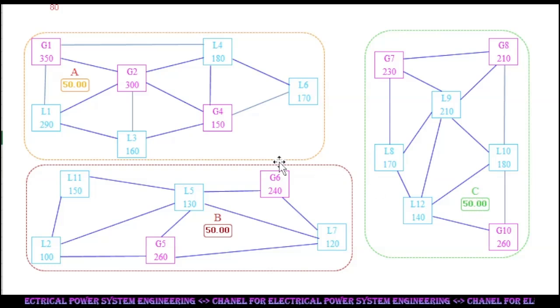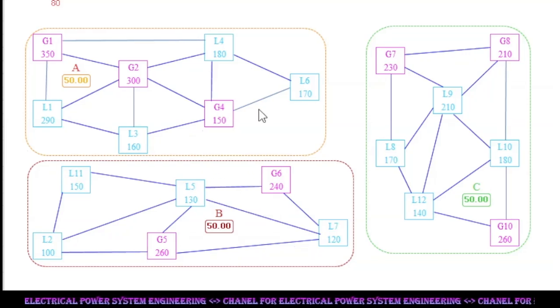Initially there are no interconnections between these power systems. Power systems are operating in independent mode. So variations in load or generation in any system affect the frequency of the respective system only. So the frequency of all three systems is monitored during the following exercise of variation of load and or generation in any system. Start with power system A.